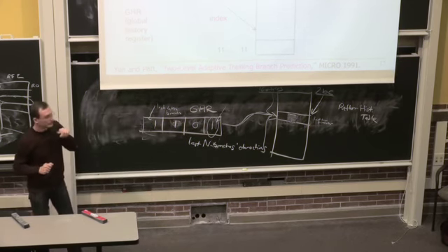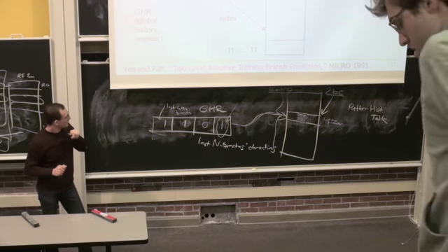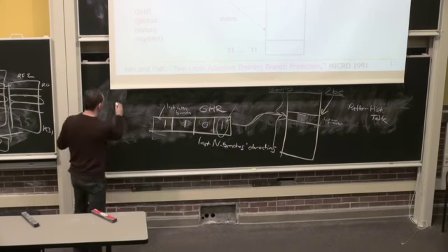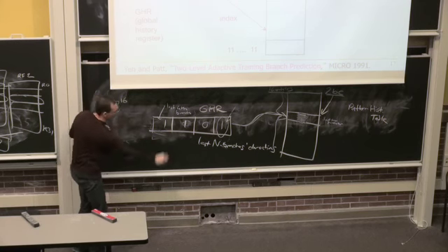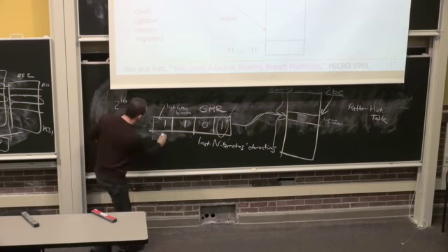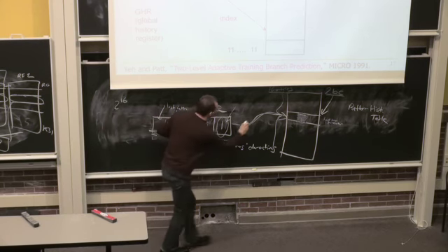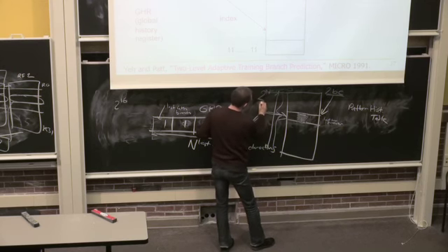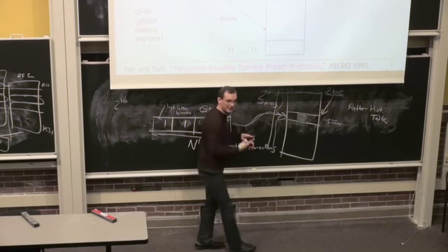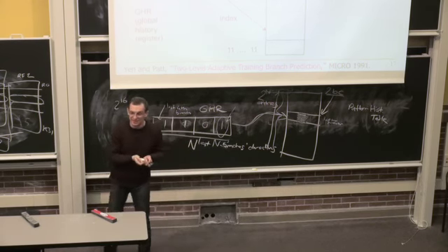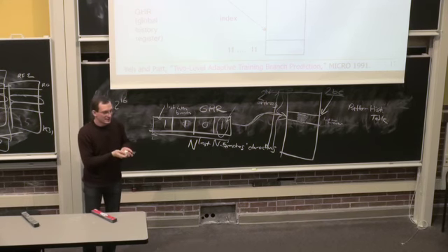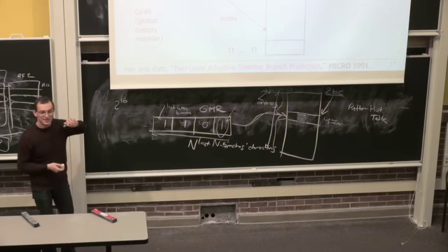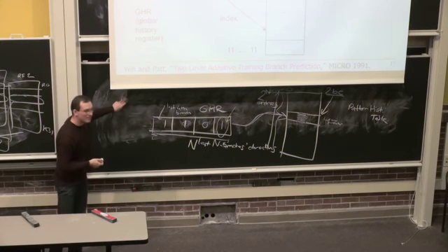Yes? If it's 16 bits, it's getting really big. Oh yeah, if you have 16 bits, then it's 2 to the 16 entries in that table. You're right. So if this is n bits, basically, this is 2 to the n entries. And it does get big. There's another trade-off over there. It takes longer to access in that case, and it becomes more costly. So that's why you may not have 16 bits. But we will see some real processors and these numbers soon.